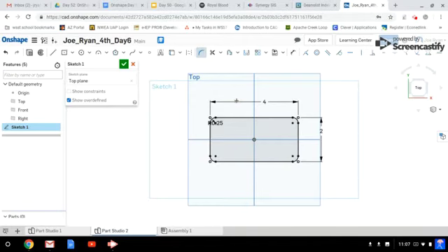So get this sketch done. So 4-inch dimension at the top using the dimension tool. 2-inch dimension at the right side using the dimension tool. And then a 0.25 inch fillet using the sketch fillet tool. Once you've completed that, please continue on in the video.